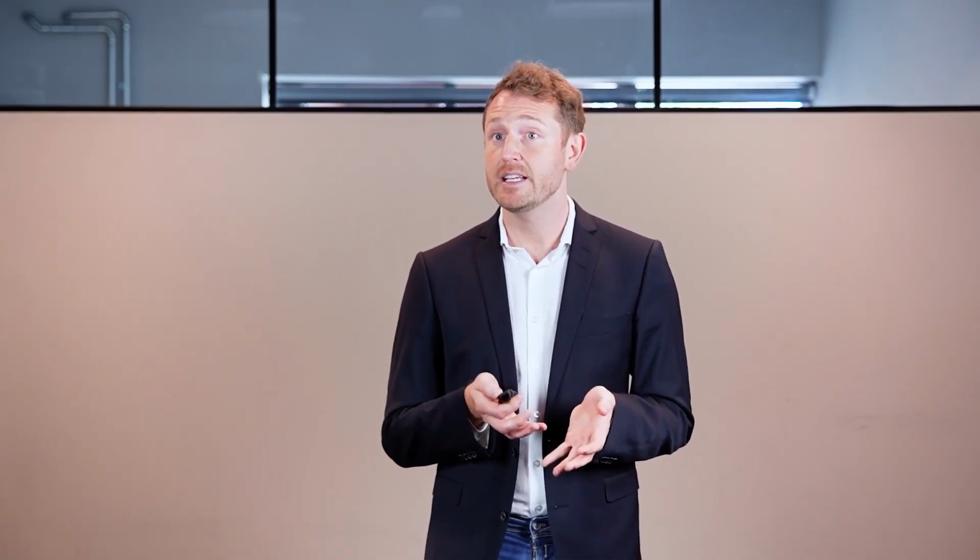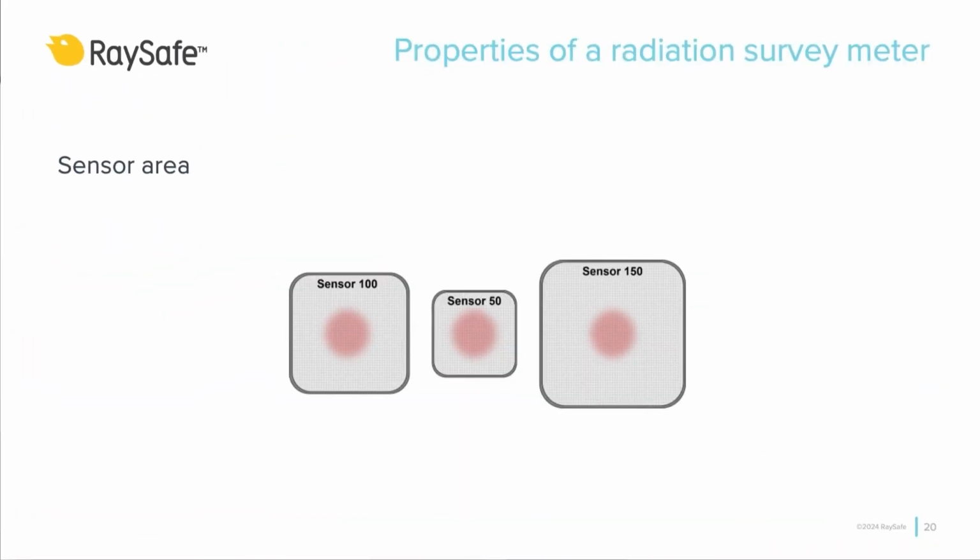One usually tries to design the meter to have an energy response close to 1 for the whole energy range. But most meters have limitations depending on the technique used. A response lower than 1 means that the meter is having a hard time measuring at that energy and would therefore underestimate the dose. Some meters have response more than 1, meaning it will overestimate the dose for some energies. Depending on type of measurements, the user must use correction factors to get more accurate readings if the response deviates from 1. Another thing I would like to mention is the size of the survey meter.